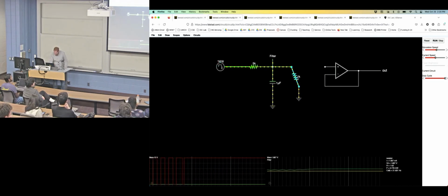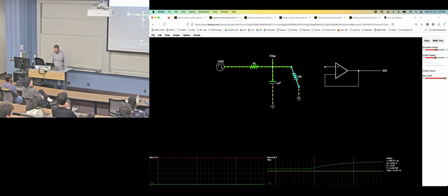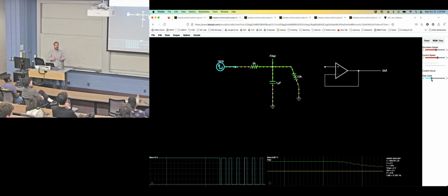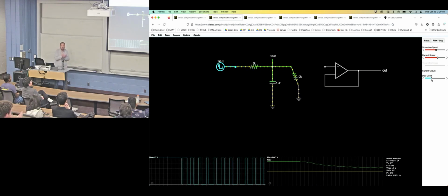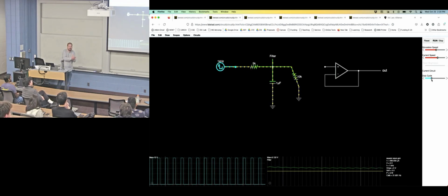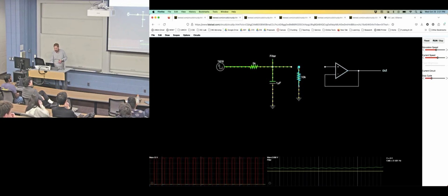Let's make this thing even a little bit larger just so it doesn't pull down as hard. Okay, so now we got some current draw. We can actually see, if I increase the simulation speed, no, current speed. You can see that this is pulling some current out of the circuit, and now my value is corrupted low, right? So your load is too high for your source to support. You're browning out your output. But if I take it off, the thing will snap back up.